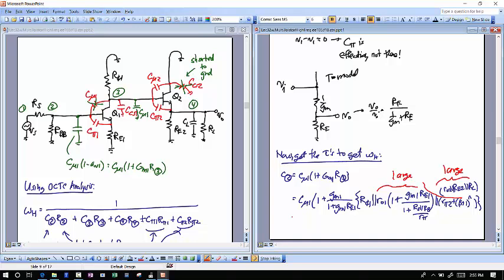And so the end result of this is going to be C mu 1 times 1 plus GM1 times that RC1 divided by 1 plus GM1 times RE1. And that's the capacitor due to that node. Okay, I spent a lot of time writing out those big resistors. On an exam, if we ask you for the explicit equation, you should write out those big resistors, but if we don't, just write down RC1. How's that resistor there? Okay? Everyone see what I did?